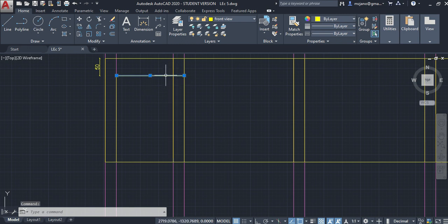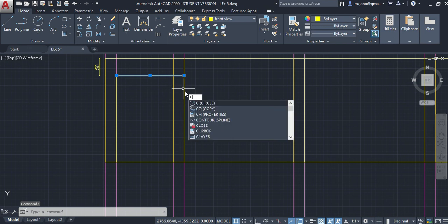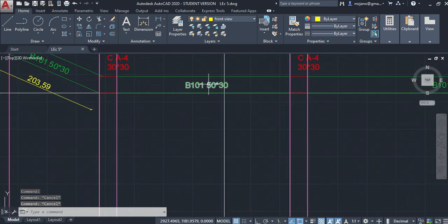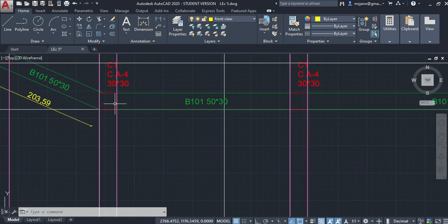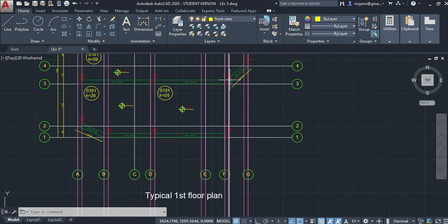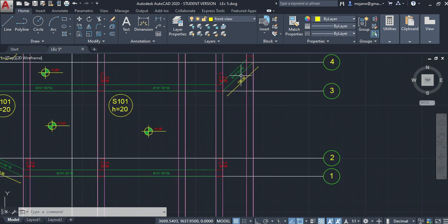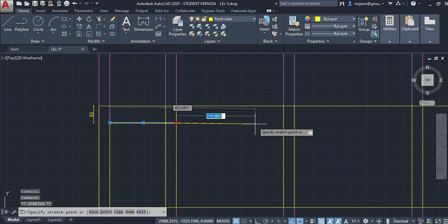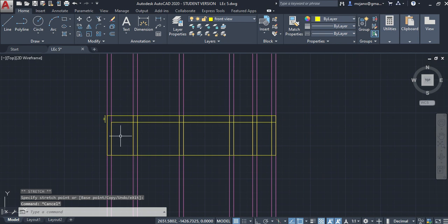Now same, because all beams have the same depth, you have from here to here also 50, from here to here 50, and from here to here this beam will also appear, right? This beam will appear because when you are looking here, there's nothing, just space. The first object you will see is this beam, also 50. So this line will be from here to here, right?